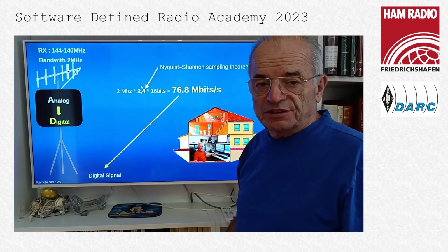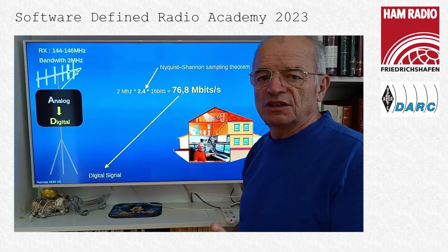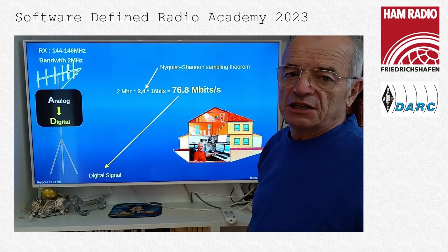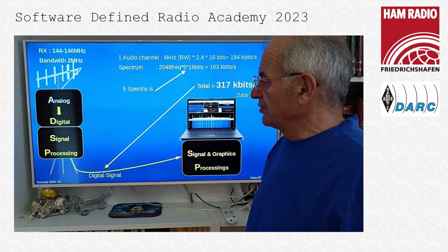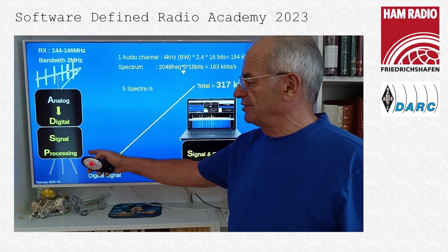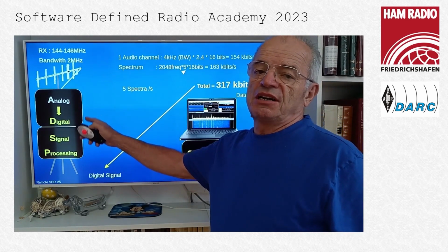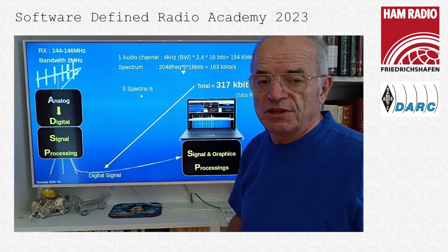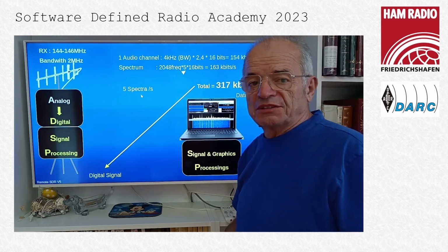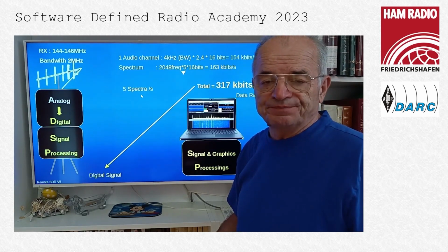This is quite important. It's feasible, but it is an important data transfer from the antenna down to your office. One solution to solve that difficulty is to add signal processing just behind the analog to digital conversion in order to reduce the amount of data transferred to exactly what we need.